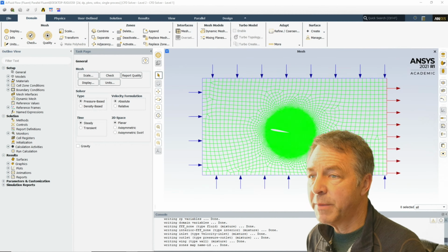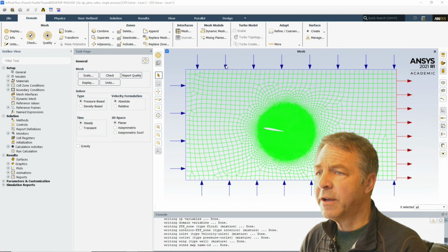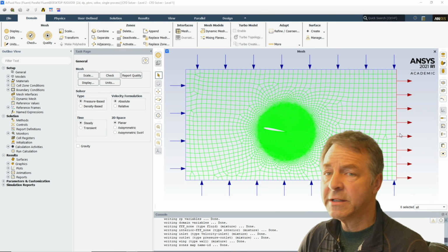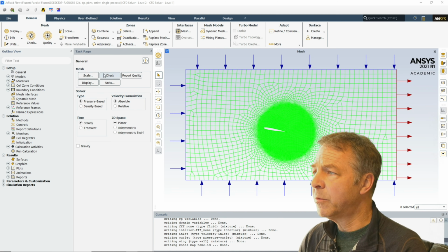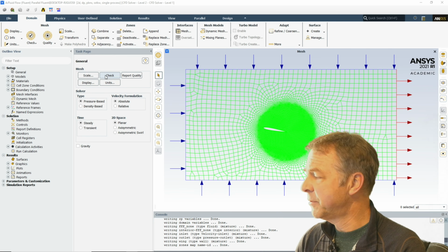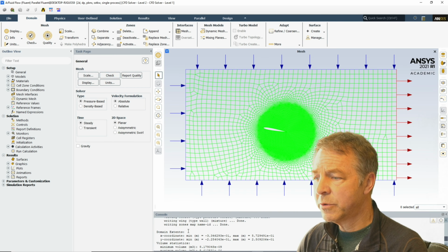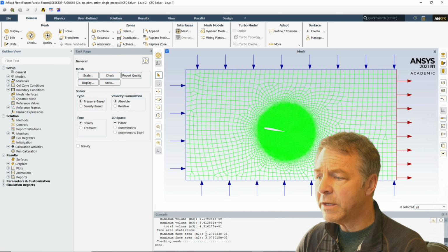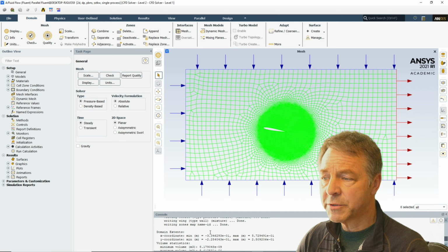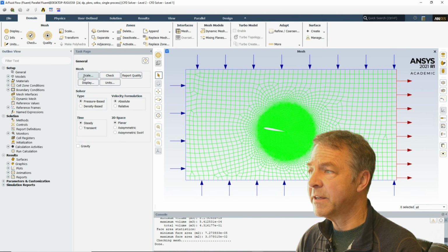And here we have our mesh, just as we had done it before. Now you can see that Fluent has already figured out that anything called inlet was an inlet and shows the arrows in, and anything described as an outlet was an outlet. So that's good. Now, the first thing we want to do is click check on the grid, and you'll see in the console window that it describes some of the statistics of the grid. And if you check that, you can look at those numbers and see that they are what you thought they would be. And if it passes that test, that's good.